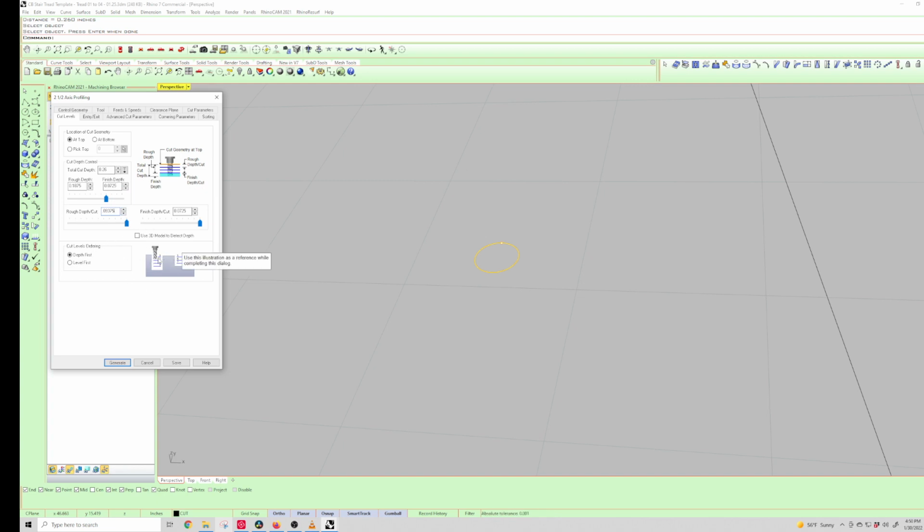This guy here, if you're cutting out a bunch of items and you don't want those to break free of the vacuum, or you want to do all of your cuts on one level. So if you had a bunch of these guys and you wanted to do all those first and then come back and do those again, leaving an onion skin, and then do a final pass with that tiny little bit so the bit isn't being loaded up, then you would hit level first, which is going to do all of the parts at that first cut, and then go back and do the second layer, and then do a final pass. We're just doing this one hole, so we're just going to leave it like that.